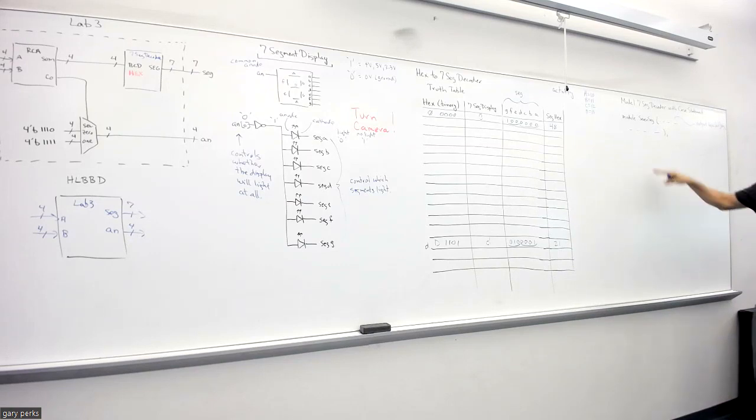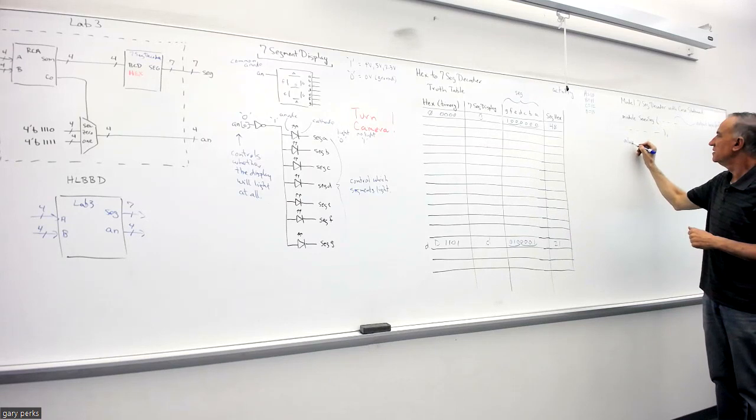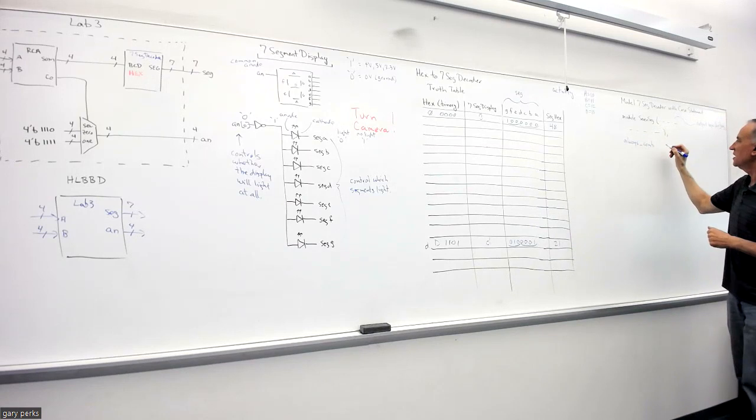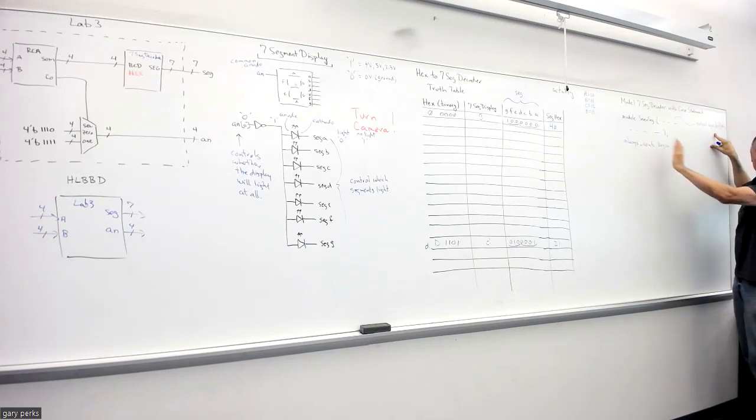All right, so then the next thing, you're going to have your always_comb, and you need the begin for it. What would happen if you don't use always_comb on the output? So you're saying if you didn't have an always_comb, but instead just wrote output logic, would it still work?